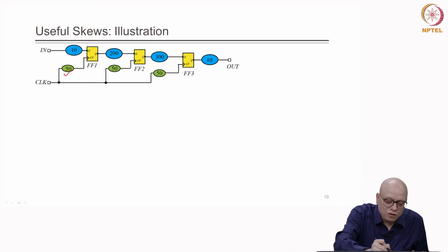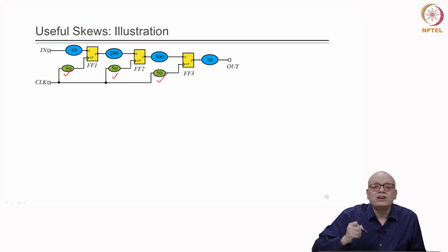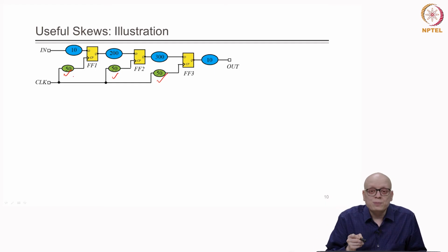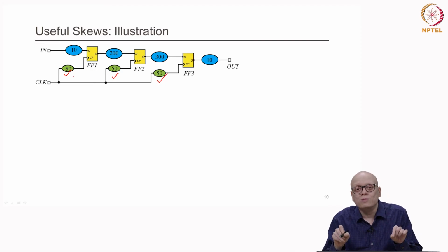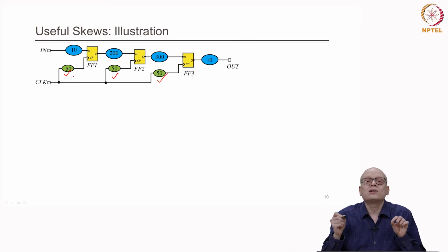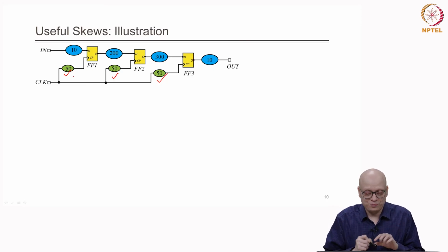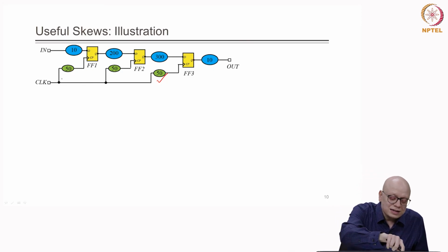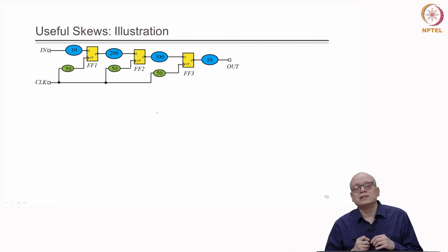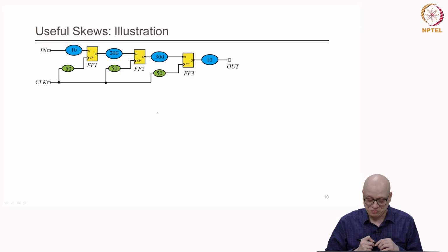The delay for all the clock pins is 50 time units. Let us assume that the time units given here are in picoseconds, right. So, we have 50 picosecond delay on all the clock paths, and since the delays are the same everywhere, the clock skew is basically 0, right. Now, let us evaluate at what maximum clock frequency this circuit can operate, right.